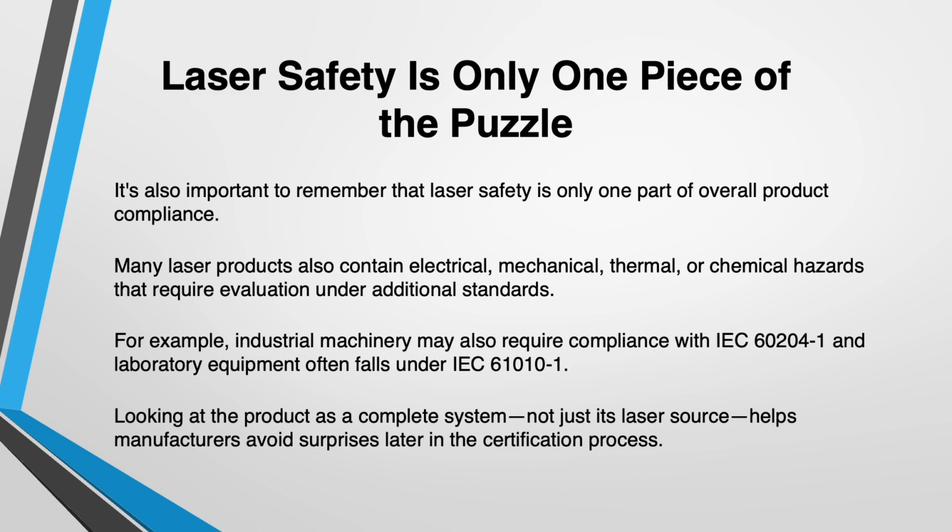It's also important to remember that laser safety is only one part of overall product compliance. Many laser products also contain electrical, mechanical, thermal, or chemical hazards that require evaluation under additional standards. For example, industrial machinery may also require compliance with IEC 60204-1, and laboratory equipment often falls under IEC 61010-1. Looking at the product as a complete system, not just its laser source, helps manufacturers avoid surprises later in the certification process.